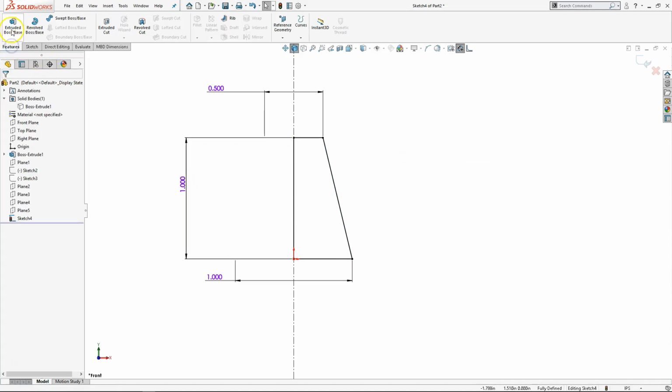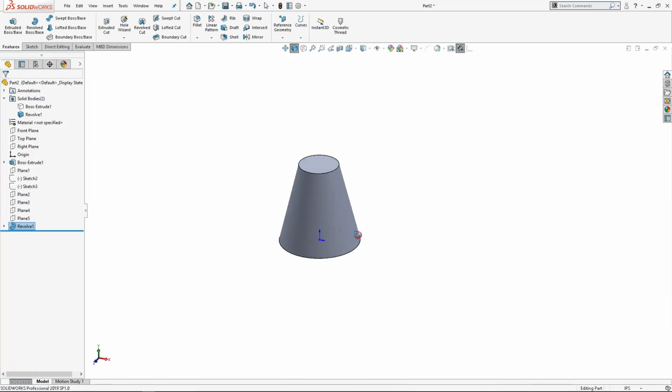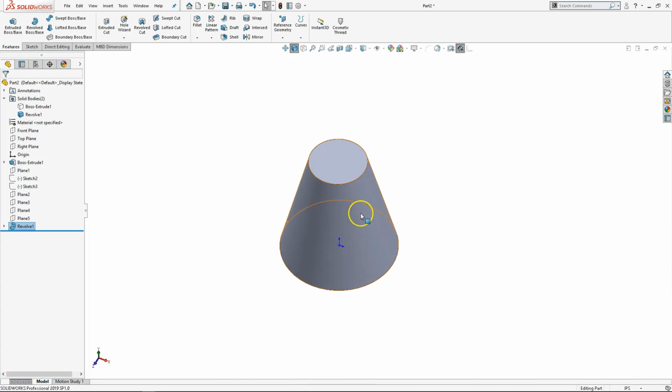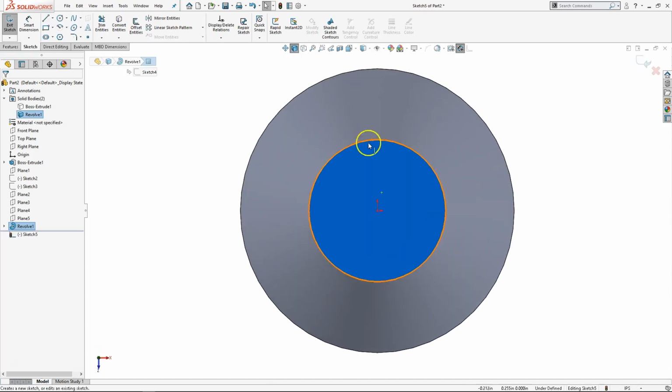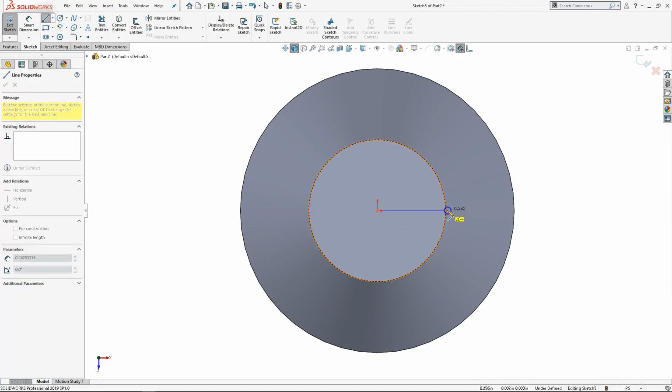All right, so features, we'll do a revolve. And if I wanted to put a Hole Wizard item, since I brought that one up, we kind of need a location, and I would like to be tangent to this surface. To be able to clock it, just saying that I'm tangent to the surface doesn't really help me.